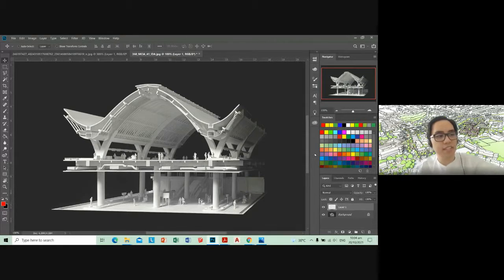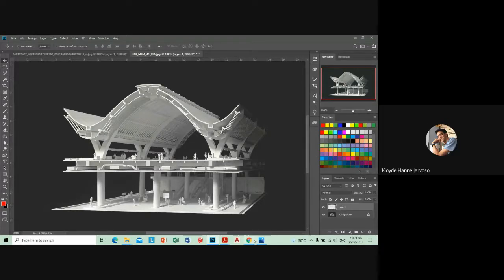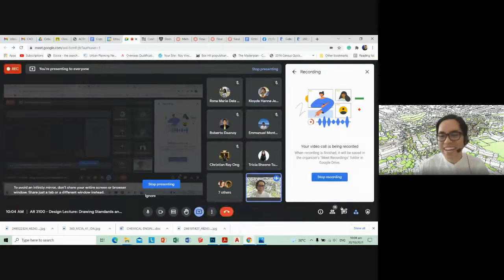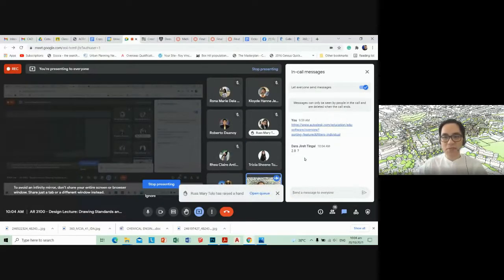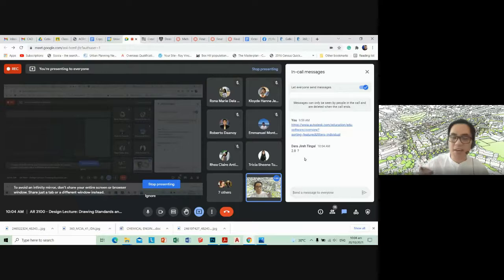Anyway, the ceiling height, sir. Ceiling height, yes. 3 meters. Is it 3 meters, sir? No. 2.7, sir. 2.7 to 2.8 is the minimum. You can go higher, so I'm looking for the minimum. 2.7 is really kind of it.